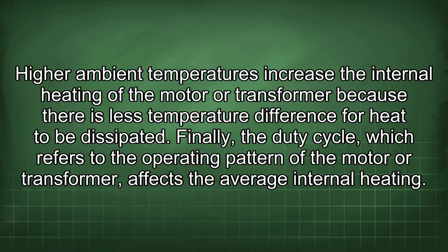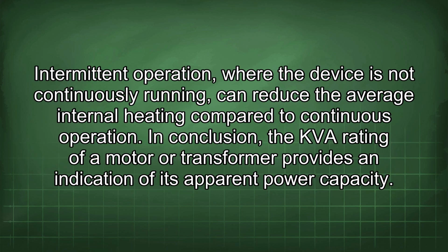Higher ambient temperatures increase the internal heating of the motor or transformer because there is less temperature difference for heat to be dissipated. Finally, the duty cycle, which refers to the operating pattern of the motor or transformer, affects the average internal heating. Intermittent operation, where the device is not continuously running, can reduce the average internal heating compared to continuous operation.